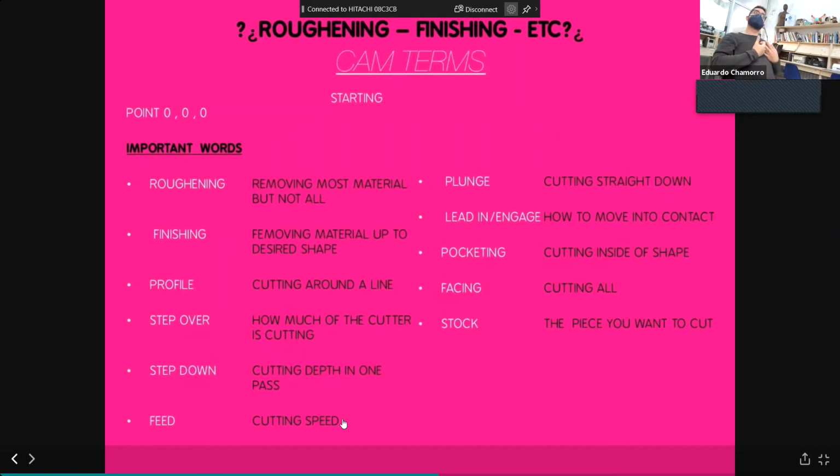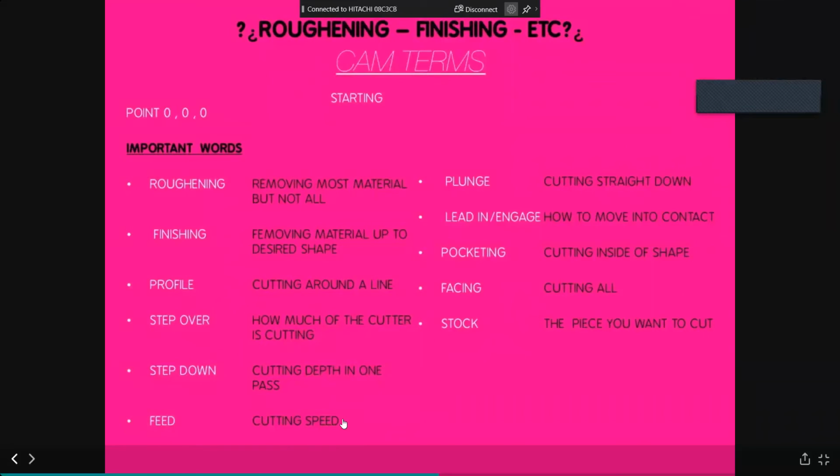When we go on 3-dimensional cutting, the feed rates will need to match. Why? Because if you want to move 3-dimensional really fast, you need to coordinate 2 different speeds, horizontal and vertical. In a 2D cut, this could be completely different. For example, for cutting aluminum, you want to plunge really, really slow, and be faster on the X and Y.